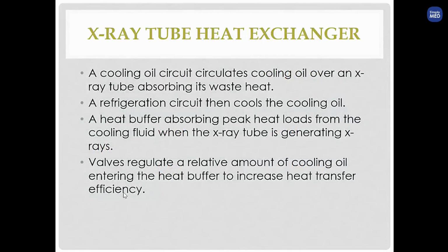Then we have the X-ray tube heat exchanger, where cooling oil will be placed to cool the tube, and there will be a refrigerating circuit which cools the cooling oil also, and there will be a heat buffer to absorb the extra heat load, and the walls will be there to dissipate the heat.